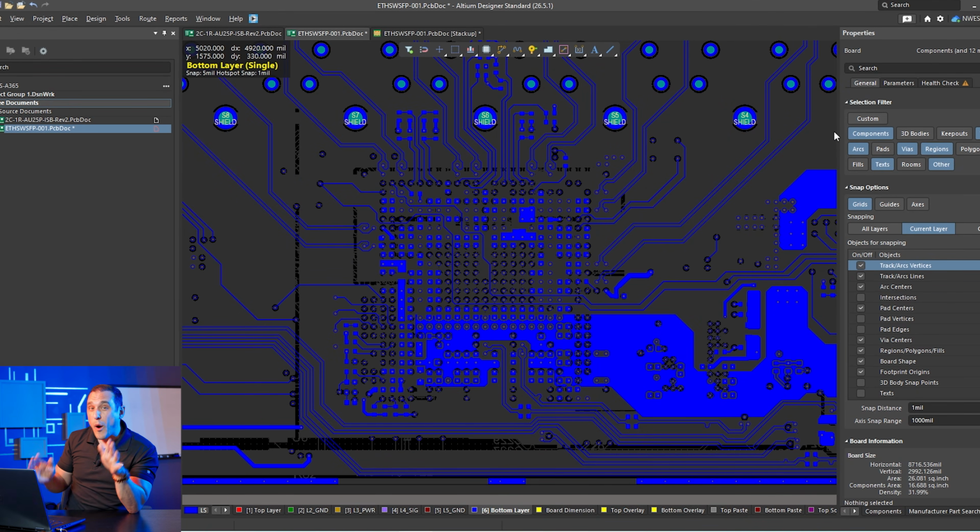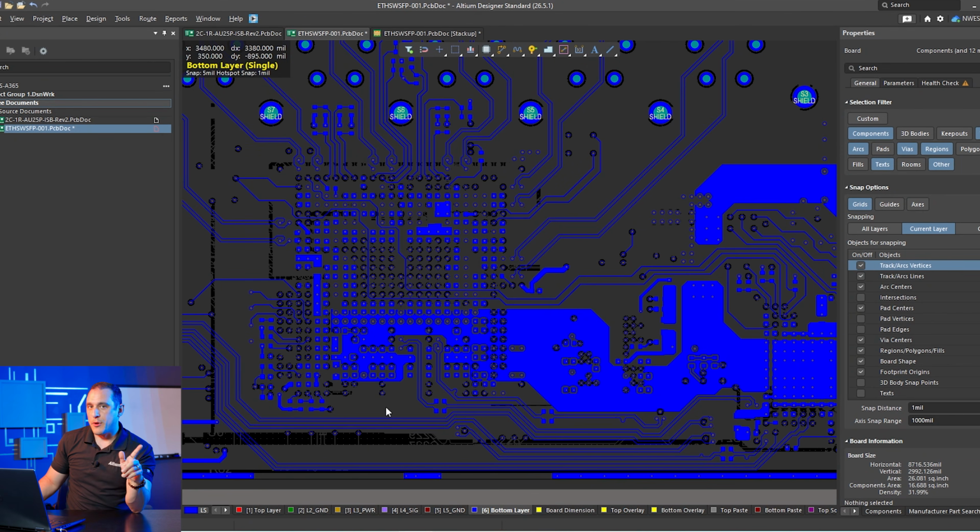Now, there isn't a requirement to do everything as microstrips. You could do this as strip line routing, and you can even do high bandwidth channels as strip line routing. In fact, for a lot of high density processors where you have high ball count, for example on FPGAs that instantiate SerDes interfaces at 10G or 25G data rates, you're probably going to be doing a lot of that routing as strip lines.